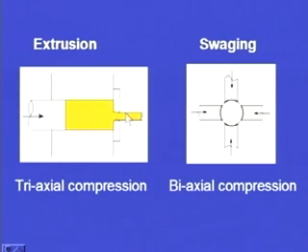Now, this can very easily be correlated to our morning process of brushing our teeth. Whenever we brush our teeth, we take a tube and press it from one side and the toothpaste comes out from the other side. Similarly, in this process, we press the metal here and it comes out through the opening or the die. The final product or shape depends upon the die opening. What type of stresses are present here? These are triaxial compressive stresses.